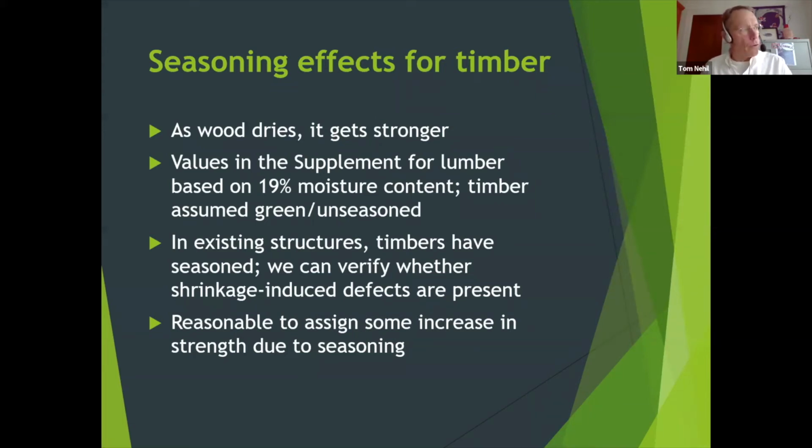They don't do that for timber. If you've got stuff that's bigger than 6 inches in its minimum dimension, if you've got an 8x8 or a 10x14, the code says you use the unseasoned green values. And they say that because, remember, they're in a new design situation. They haven't seen the stick. They don't know how it's going to dry. Maybe some defects are going to develop. It's going to shrink and get smaller. So as a conservative approach, they say, we'll just take it as green.